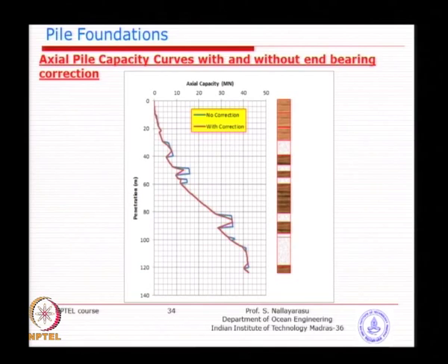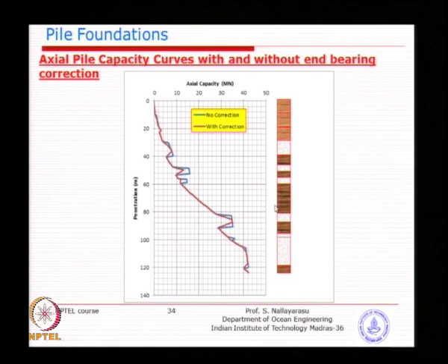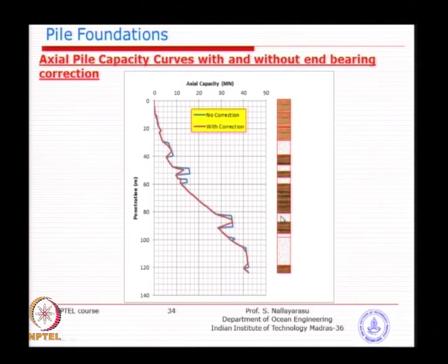No, you can see the blue color, the same layer gives you a lower capacity, because you are using the capacity of the clay, and the same location if you go to this using this property of the sand, you get a higher capacity. Which one to take? That is where the biggest problem is. So, we will normally do a linear interpolation with acceptable penetration depth into the sand layer. So, that is where we are going to see 3 cases.